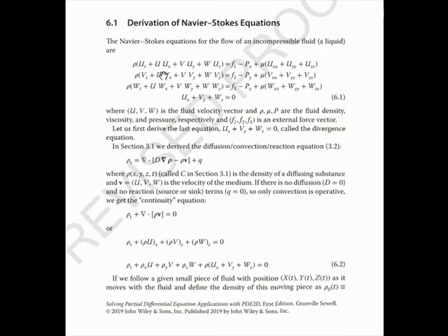Okay, so these are the Navier-Stokes equations. There's 4 equations. This is the divergence equation that basically says the fluid is incompressible. This is what you get by setting the density times the acceleration equal to the force field acting on it. But now, if you try to solve this system of equations in 2 or 3 dimensions directly as written, you'll not have much luck with either collocation or Galerkin method or most any method. Just brute force try and solve this. It's almost impossible.